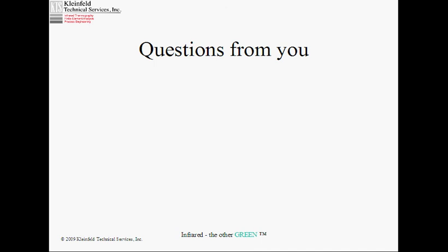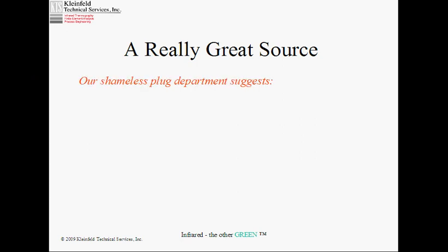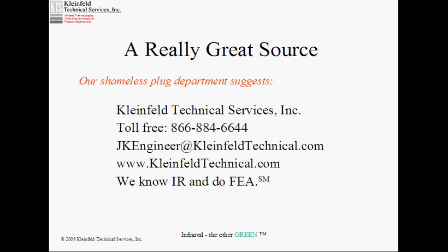One of the things that they do on above ground tanks is you can look at the tank again under the impact of the sun and cooling, and you can see where the liquid levels are. You can differentiate between the foam on top of the liquid itself, and the sludge under the liquid. And they use that, for example, to say, we need to shut the process down now because we've got more than 20% height of sludge, and we're going to need 12 containers to take the sludge away versus the 2 containers we thought we would need. So they're ready for the shutdown in terms of having logistics arranged. So yeah, under some circumstances, yes.